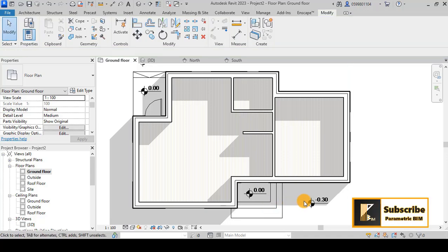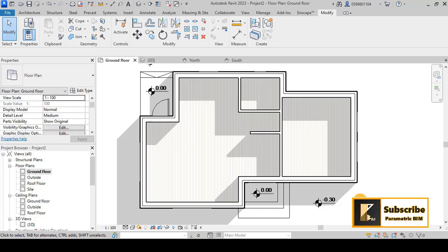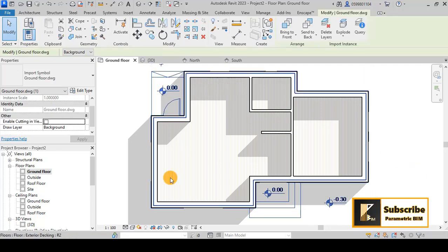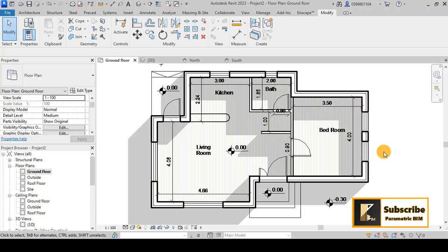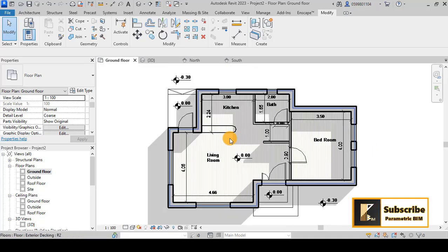You can simply have many ways to do that, and let's say show your windows in order to also put the windows in Revit over them. You can choose the imported and then come here to the properties, and as you see for others here we have draw layer, which is background. You can simply go with foreground and you can see your windows over the walls. Even if you have coarse here, you can see them also. But there are also other approaches.